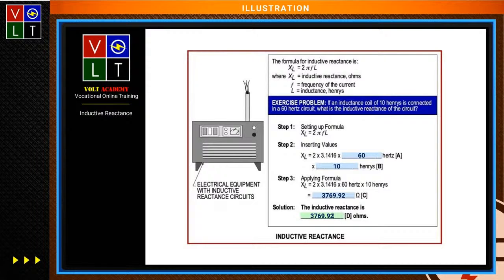Okay. And as inductance is increased, that induced electromagnetic force that opposes the applied EMF is increased. Therefore, the flow of current becomes what? It reduces. And that's what you're talking about. Depending on if you're capacitive or inductive, that's what those engineers are looking at. And that's why you got that 30-degree angle there.